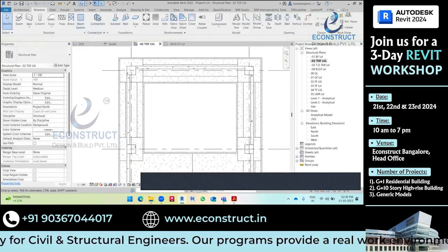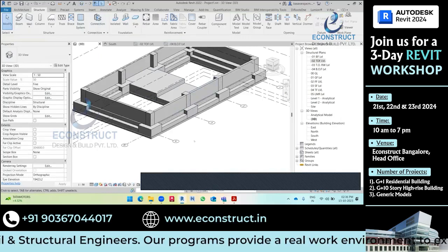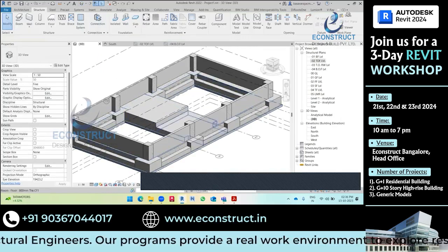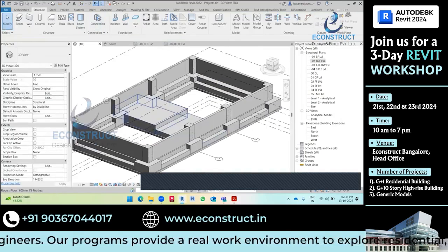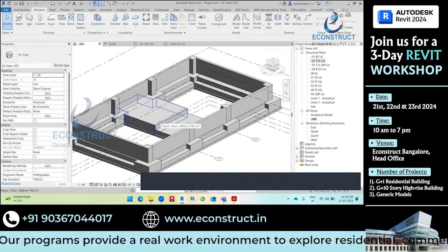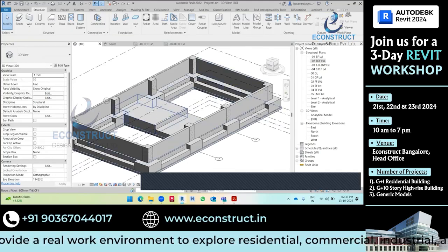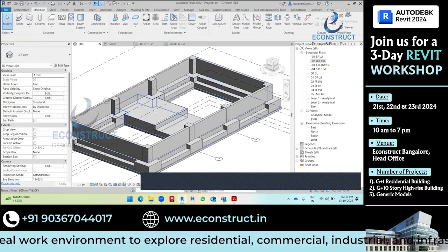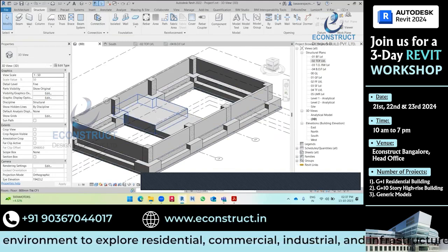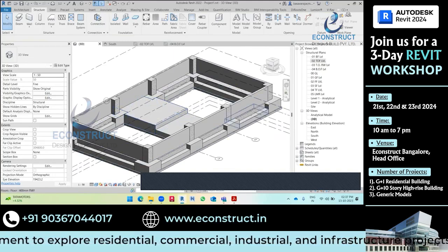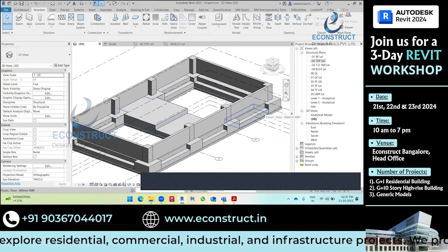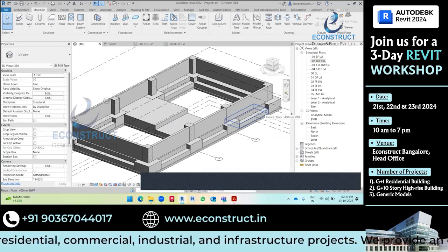Okay, if you go to 3D view, see the wall, it is like this now. So our foundation level up to the basement floor level is completed. Now we need to draw the lift well wall. Before that, we need some reference lines, center lines for the lift well wall.